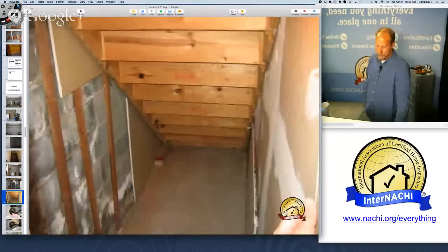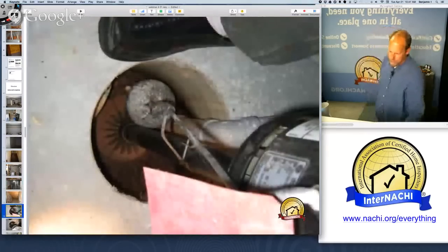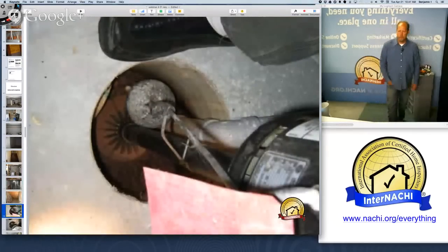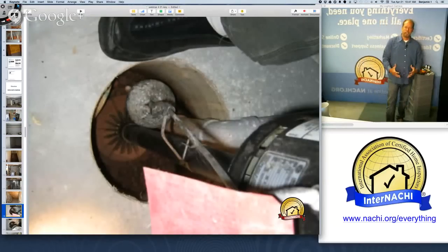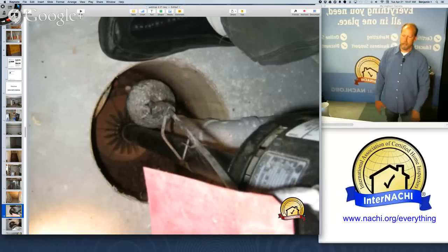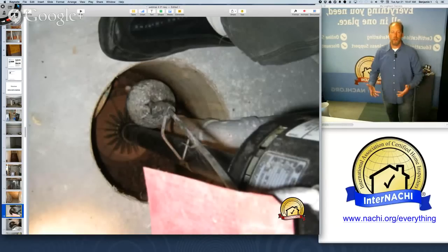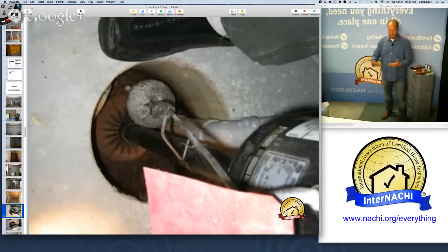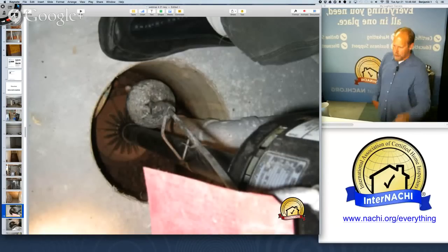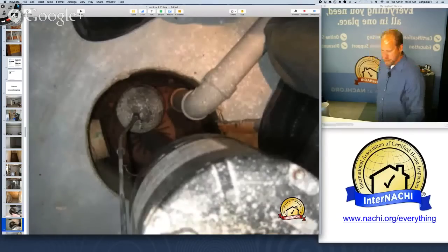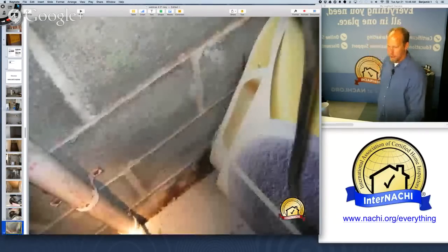There they are. The sump pump: in a lot of areas of the country, you have a perforated bucket essentially filled with gravel. Water underneath the floating slab in the basement finds the lowest spot and fills up the bucket. There's a float on a pump, and that pump turns on and discharges the water outside. So that's a sump pump.